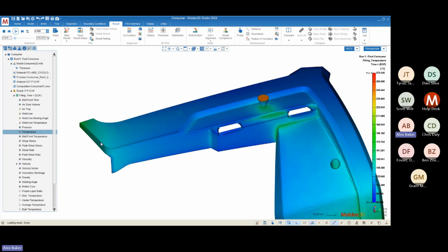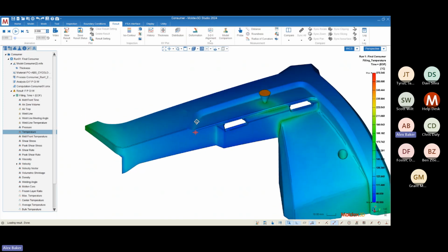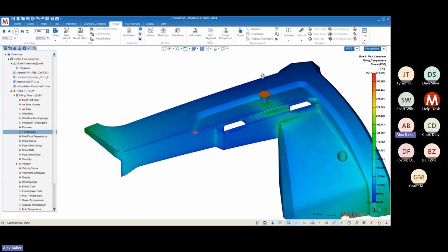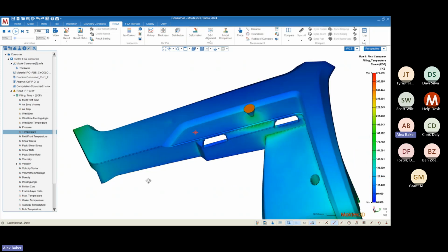There's actually this balance that's occurring. Energy is constantly being released out into the mold, but the movement of the material is also converting that energy into heat as well. Right? So there's a heat generation effect, and then there's a heat release effect. I usually like to call it the cooling effect and the shear heating effect for simplicity. Which of those effects dominates is going to dictate whether our temperature increases over the length of fill or decreases over the length of fill.